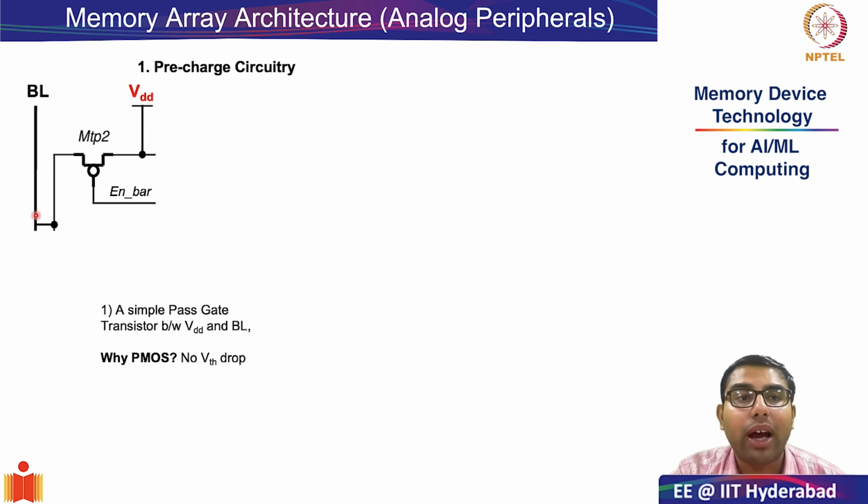Please try to recall why we use the term charge the bit line: although the bit line is one long interconnect, it has both a resistive and capacitive element. The capacitive part of the bit line is generally represented as CBL, C standing for capacitance. And the idea is that I would like to charge the bit line for a read operation to VDD.